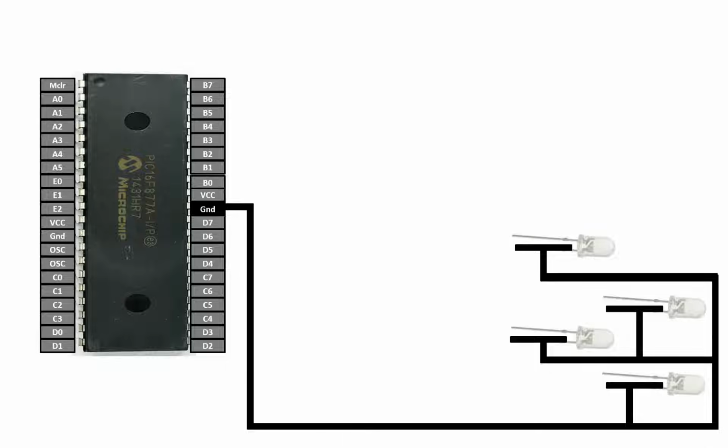Now guys, for the longer pin, you will need a safety resistor, 1 resistor for each LED. So 4 LEDs means 4 resistors. Now this resistor value can be any value from 100 to any value that you prefer, because the higher the value of this safety resistor, the dimmer the LED will go. Now it depends upon how bright you want your LEDs to be, so select the resistor accordingly. This resistor will be a safety resistor. It will limit the current. Without this resistor, there is a chance of getting the LED burned. So I'm going to use a 220 ohm resistor because it's an ideal value. I need the brightness of that value.